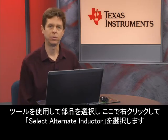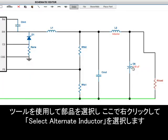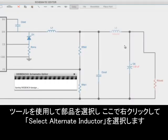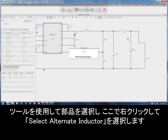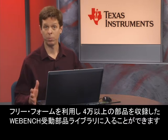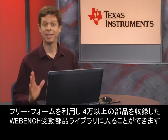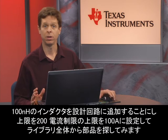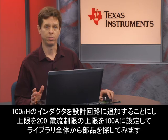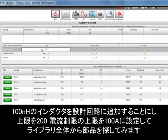Now I'm going to use the tool to select my component. I just right-click here and choose Select Alternate Inductor. You can now take advantage of free-form access into the WEBENCH passive library, which has more than 40,000 components in it. So here, I will put a 100 nanohenry inductor into the design. So I'm going to set my upper bounds of 200, my upper current limit at 100 amps, because I want to look at the entire library.